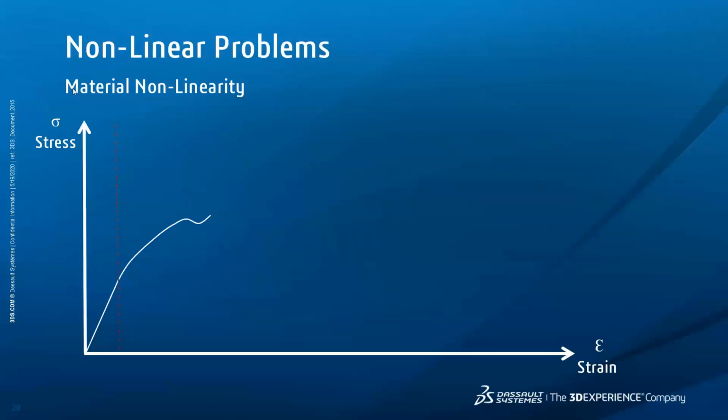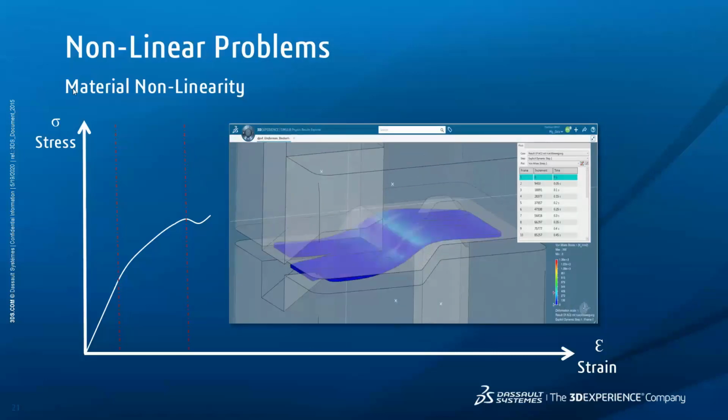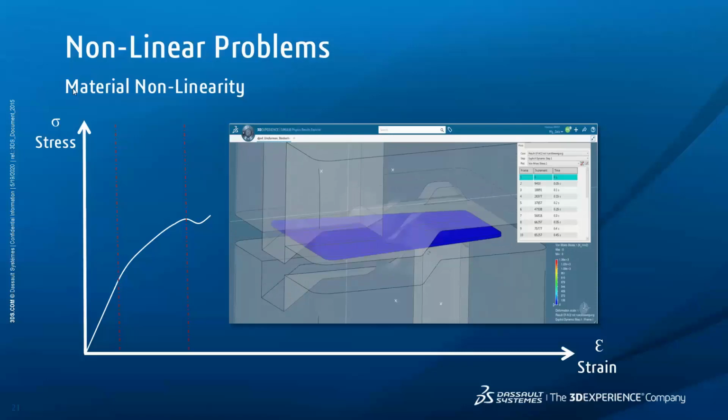Depending on our material, we may see a yield as a single transition. However, we may also see yield regions with distinct upper and lower yield points. It's important to understand this mechanical response, particularly when investigating strain hardening effects during manufacturing processes. Here we can see a multi-step metal forming process, which relies on an understanding of not only when we see plasticity, but also whether any hardening effects are taking place. With SIMULIAworks, we are able to model not only isotropic hardening, but also kinematic hardening when witnessing cyclic loading.